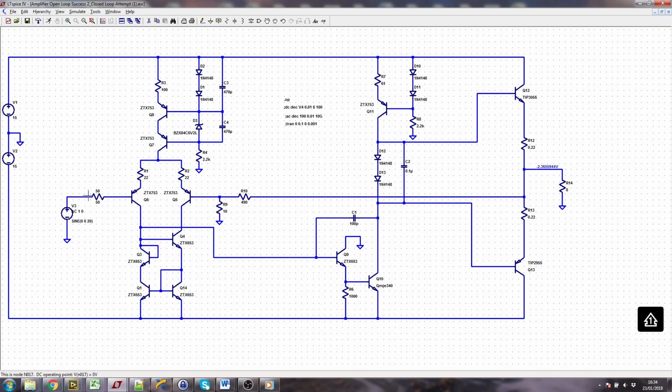Now the current that leaves here sees this voltage, and because the base current leaves the 753, the PNP, it will set up a voltage across here, and the source, I can imagine, is switched off at the moment. So 50 ohms to ground. This one sees 10 ohms to ground and whatever funny parallel we've got up here. 490 plus 8, more or less. So we might need to deal with that first. Then we'll see if this is at fault. And if it's not, we'll consider this again. And if this voltage is held too high by these transistors. And if it's not this, we'll go and inspect that, and we'll keep going until we figure it out.